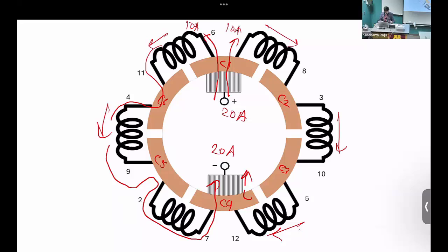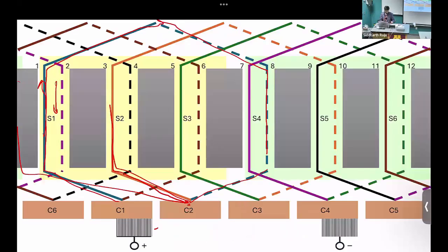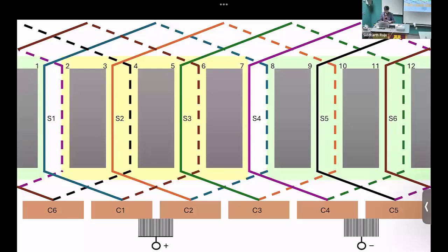All right. So now we are going to look at the rotor start to rotate. As it rotates, these windings and the commutator segments are moving with it, but the brush is remaining at the same place. So instead of changing the winding diagram, I'm moving the commutator in this diagram. So the brushes, I'm moving in the forward direction, but it's actually the rotor moving in the backward direction, right? So once we come to this point, we are basically shorting conductor 1 and conductor 8.